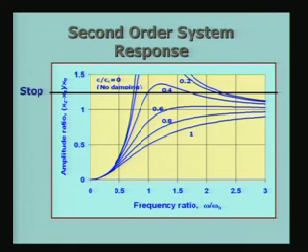The second point I would like to mention here is that, if you remember, in the previous lecture we indicated that we can limit the amplitude of the vibrometer or vibration sensing device by putting stops. So, if I put a stop such that it is not more than, let us say, 1.25, then you see the kind of behavior you are going to get for different damping ratios. For example, if I do the experiment with C by Cc equal to 0.4, it will go up to this, and when it hits the stop it is not going to change. So, it is going to stay constant, and then it is going to come back like that. So, one way of preventing the runaway of the transducer is to put stops, so that the amplitude is limited to a certain value. In this case I have taken 1.25, you can put it even less than 1 or more than 1 as the case may be. That will prevent the vibration sensing device from executing too large an amplitude and probably wrecking the sensor itself.